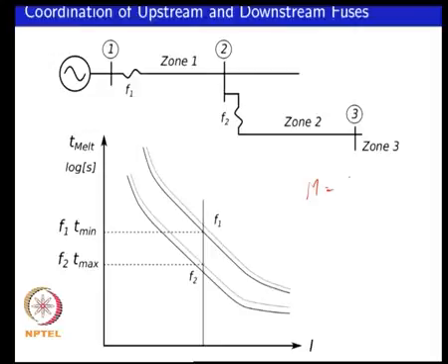melt ratio, as your actual fuse current divided by the melt current. So, as long as the current is below this melt current, the fuse is not going to get damaged. Once you go above that particular melt current level, you have a possibility of the fuse melting, and the time required to melt would now depend on the value of the current flowing through the fuse. Okay.